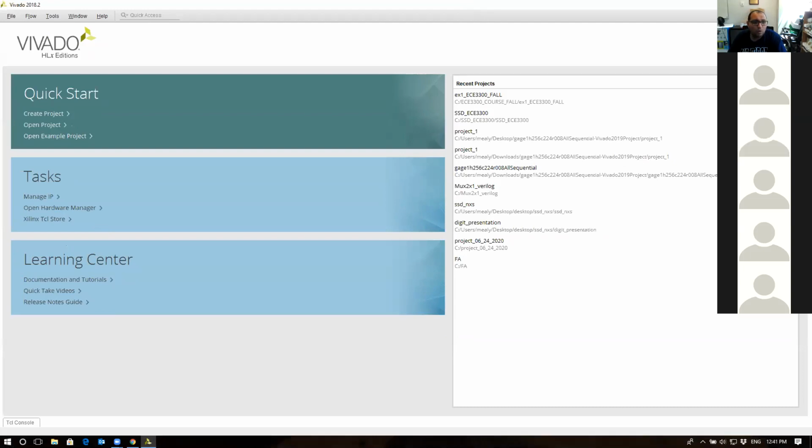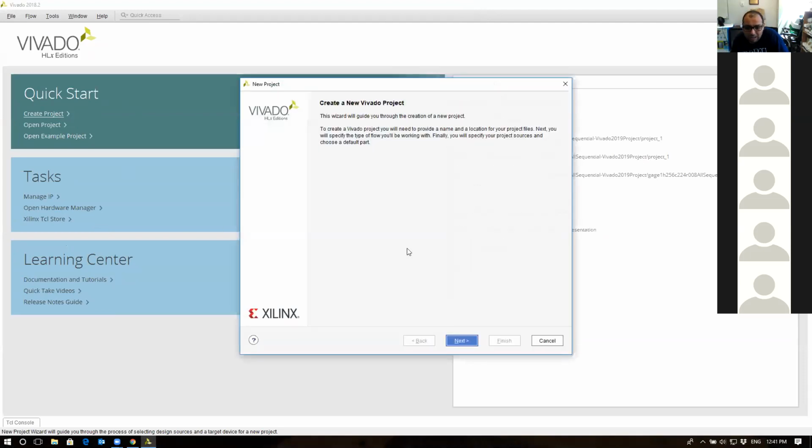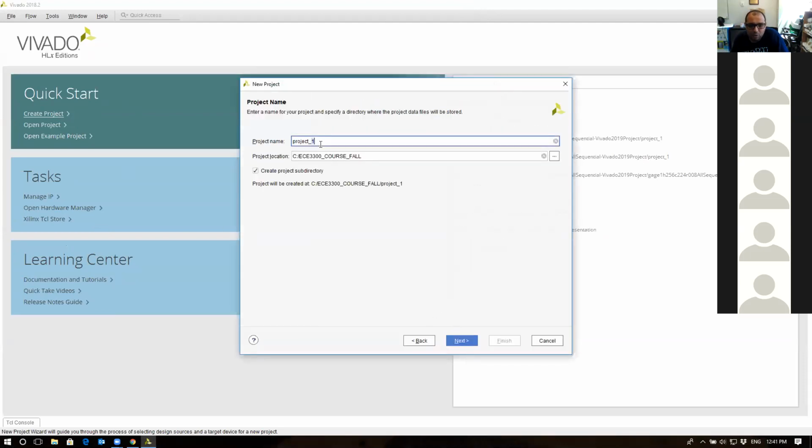Okay. So normally when Vivado opens, you say create project. That's the first thing, unless you have a project you would like to resume. So you say next. I'm gonna call the project with a name. What name can we call the project with? Let's say, whatever, full adder. Then next. It's gonna be stored in the ECE3300 course underscore 4, okay?